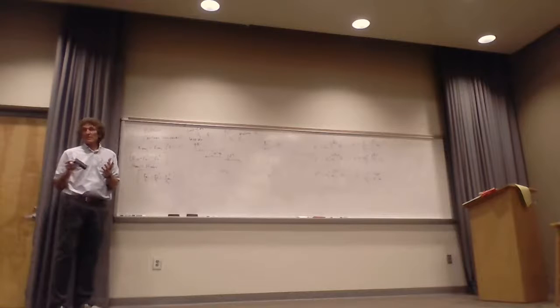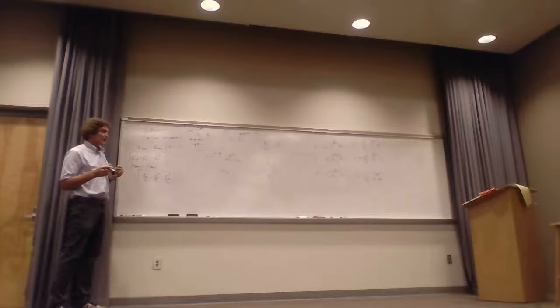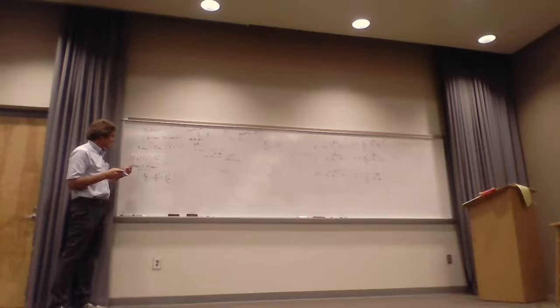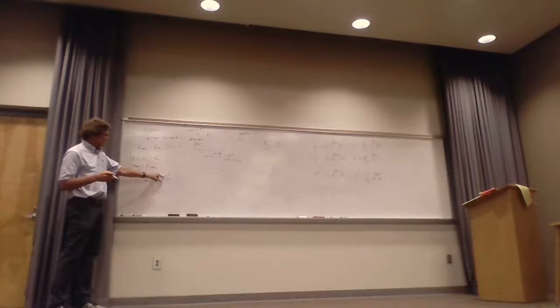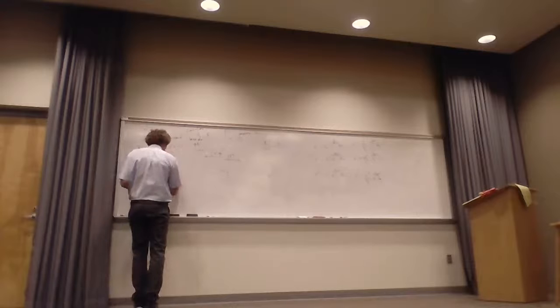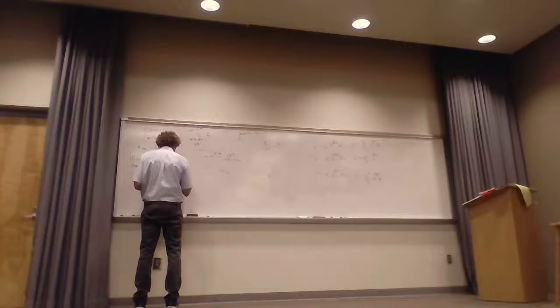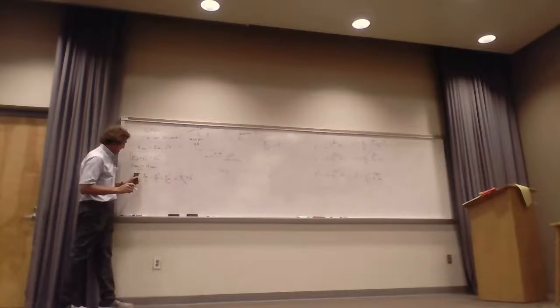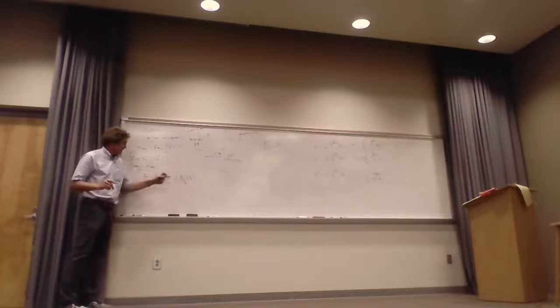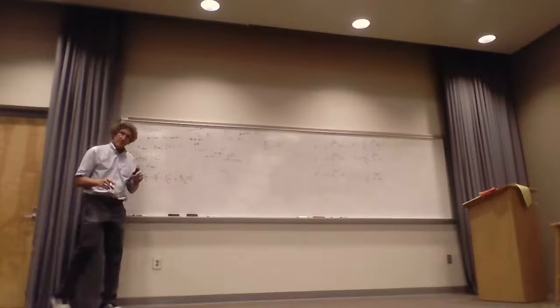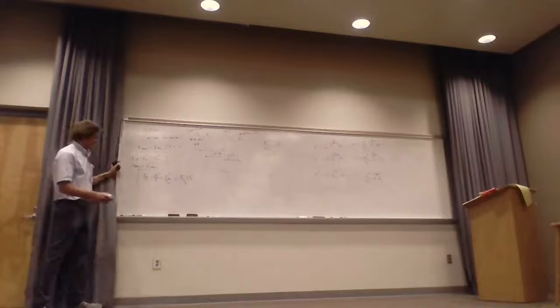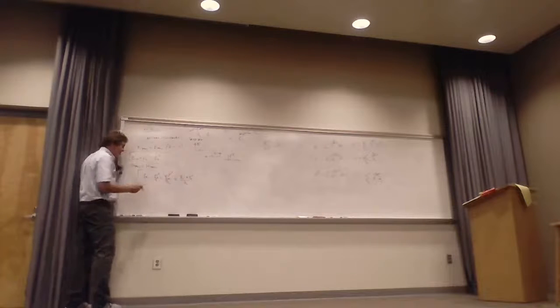But what I really want is to solve for a ratio of the reflected to the incident field. So if I take E naught transmitted and put it in here, then this becomes E naught incident plus E naught reflected over eta 2, which is equal to this. Now I have E naught incident, E naught reflected, eta 1 and eta 2. Y'all with me? You don't have to look at this middle part.